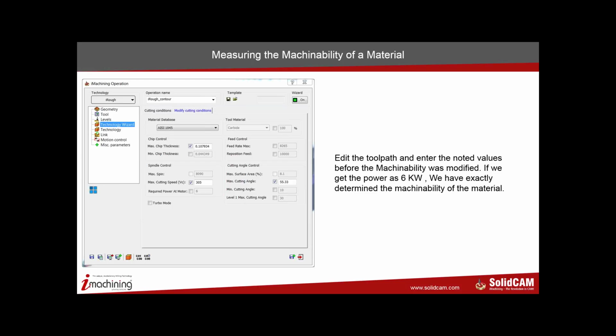By doing this, you can be assured, 1, your cutting will be much better. Number 2, your tool life will be what we always say, 3 times, 4 times. And the surface quality is going to be much better than what you would have got with that value kept at 0% and not minus 16%.